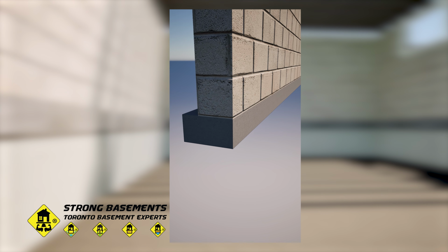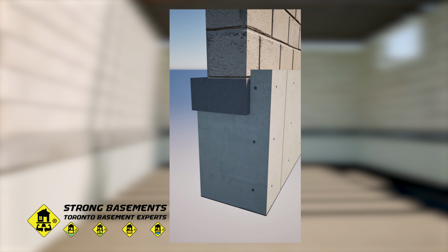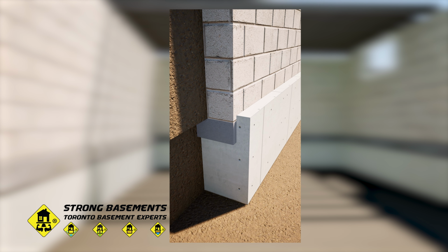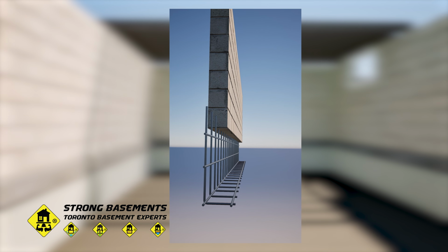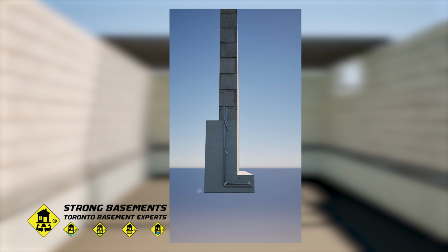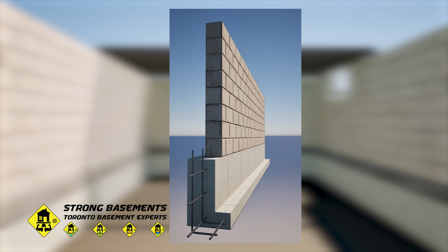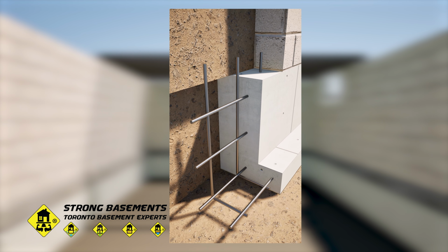While the overpour method is the most cost-effective, it's generally only an option if you're lowering the floor by less than 24 inches. On the other hand, the L-shape method is more complex and carries a higher price tag, but it's the best way to eliminate the bench, underpinning flush with the foundation wall, and maximize every square inch of your usable floor space.